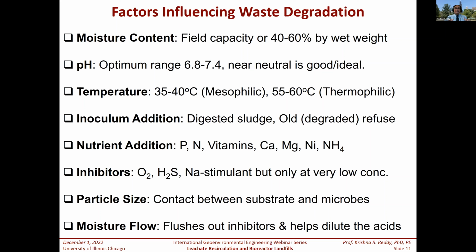If you use any kind of liquid waste, for example industrial liquid waste, landfill owners like to do that because they can generate revenue for themselves, right? If they can accept the liquid phase from industries, which is very hard to treat, and use it for recirculation, but make sure that these conditions are maintained. You don't want to, for example, get some industrial liquid that has a lot of toxic metals, and you may be killing the microbes. So you have to be very careful in terms of what liquids you inject.